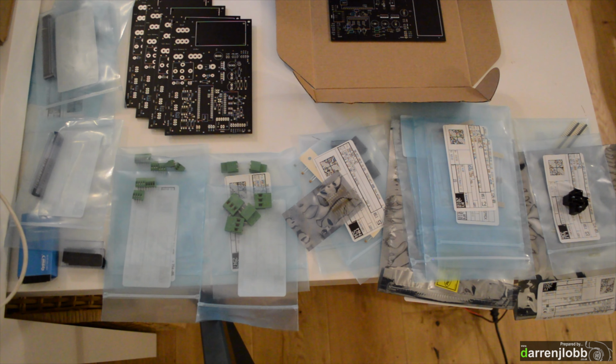So as I was just saying, you can actually use the Gerber files in that directory to create this board exactly as you see it here. A company like JLC PCB, you can basically send them the file, they'll manufacture and even test the board for you if you want, and then post them to you. It's super simple. It takes literally 10 minutes and the delivery time is pretty good.